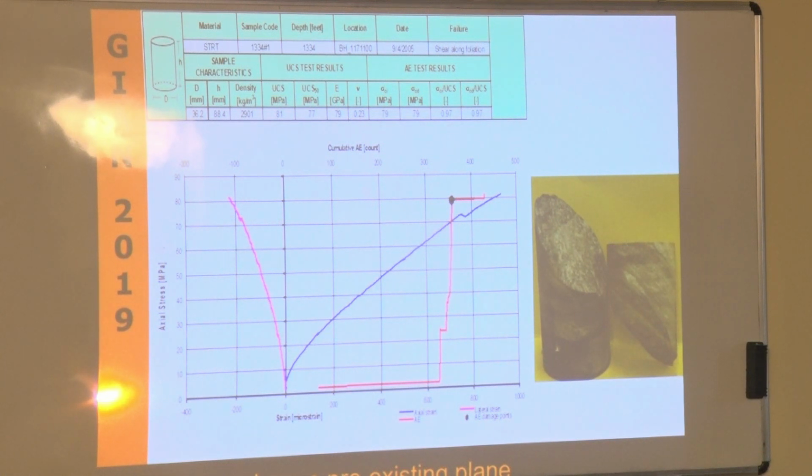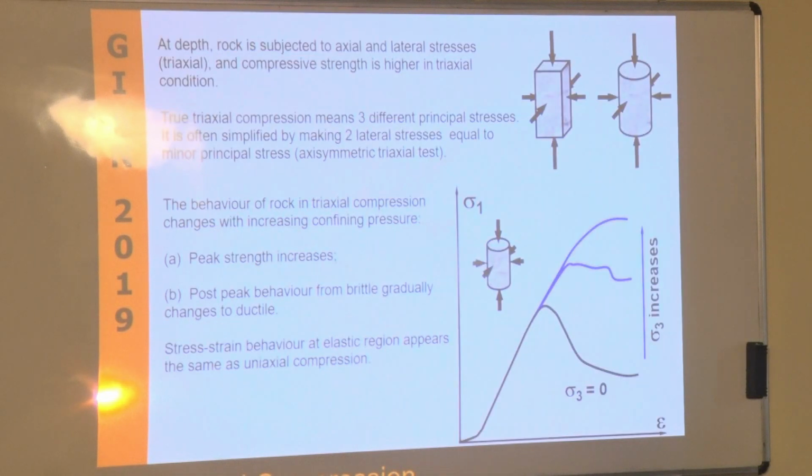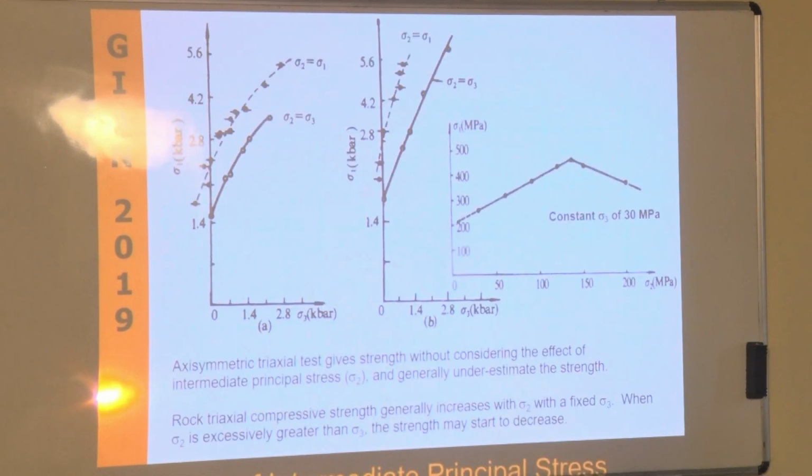And for me, the Poisson ratio is always one of those values that is not a value, it is a function, and that is very hard to estimate. It is one number for which you need to have a lot of engineering judgment when you pick it for your models. That is my warning, and that's from experience.